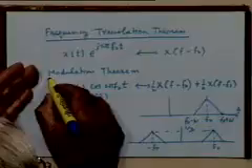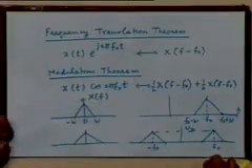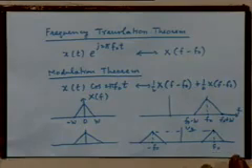Now these theorems play a very crucial role in modulation techniques that we are going to discuss in this course. In fact, it forms a basis of one of the most important functions of the transmitter, namely to modify the center frequency of a signal. This is also very useful in receivers when we want to bring a signal from an RF frequency down to a baseband frequency.